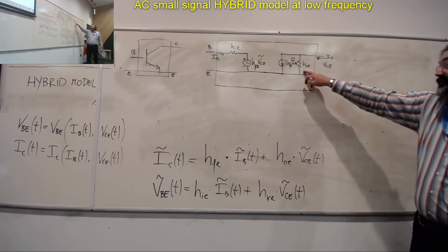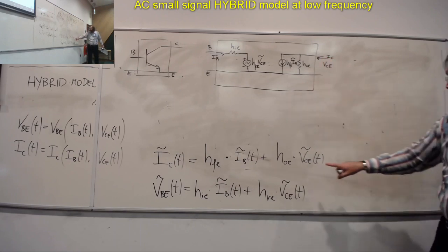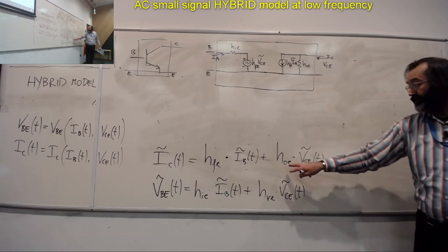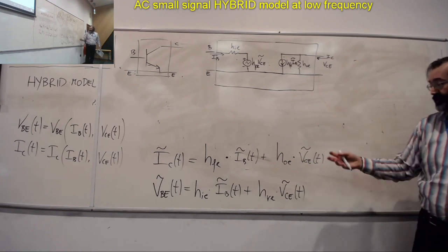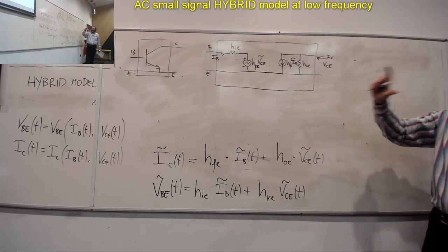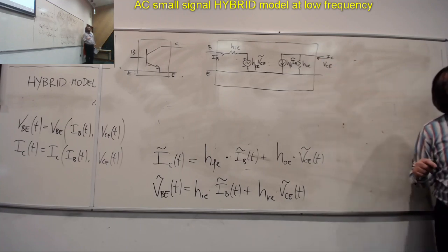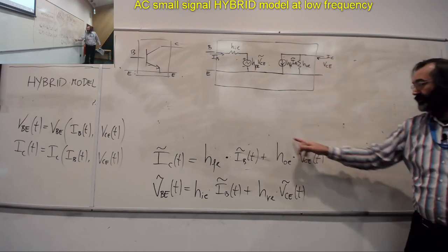And this resistor, or well, HOE, remember, we said is a conductance, so it is the inverse of a resistance in value. But it has to be placed like that because of the way it appears here. Because HOE, you see, this is a current. This is the current that is flowing through a resistor that has applied to its terminals VCE. And that's the only way it can be. The current that is flowing through here is representing this term.